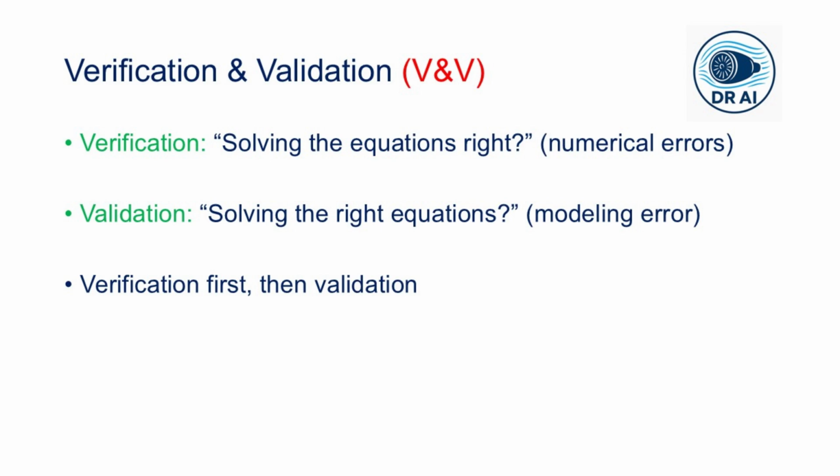While in validation, when we ask are we solving the right equations, we compare the simulation results to reliable experimental data, typically done for a specific class of flows, for example the turbulent flow over a backward facing step. It also quantifies the modeling error. So the important point here is that verification must come before validation. A non-verified code or an insufficiently resolved grid makes validation meaningless.